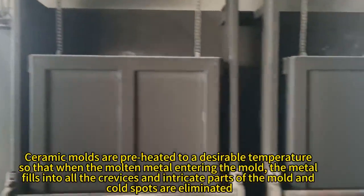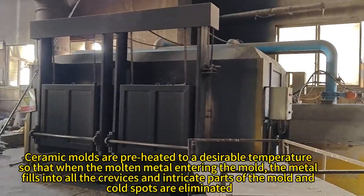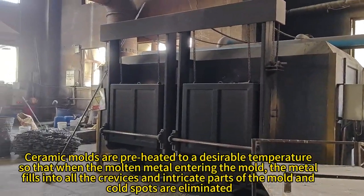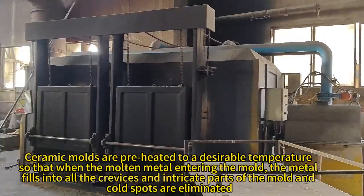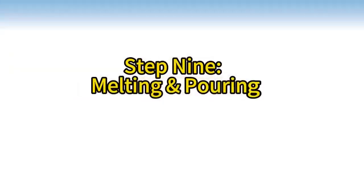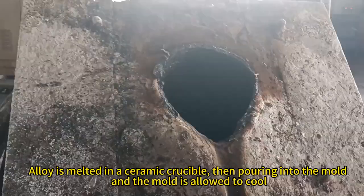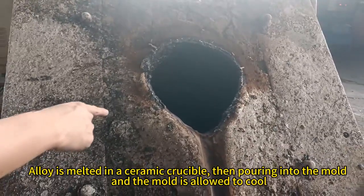Ceramic molds are preheated to a desirable temperature so that when the molten metal enters the mold, the metal fills into all the crevices and intricate parts of the mold, and cold spots are eliminated. Step 9. Melting and pouring. Alloy is melted in a ceramic crucible, then poured into the mold, and the mold is allowed to cool.